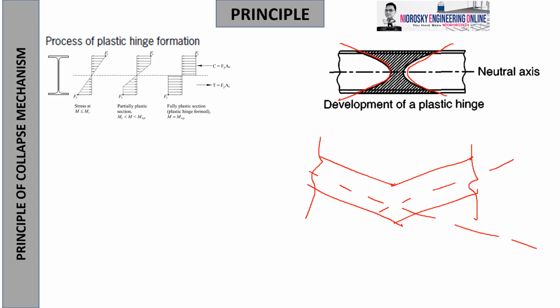Okay, ito yung may kinalaman sa theta sub P, let's say, or plastic hinges. So, dito, meron ditong imaginary ball point na kung saan nagkakaroon ng tinatawag nating hinging. Yan yung pagkatupi in other term. So, yung pinapakita ng region, I'll try to shade it in red. Kinukulayan ko ng pula so that you would better view, or we can try violet para makita. Pinagsama ko ng violet at red para a darker color may exist here. So yan yung portion na natutupi where plastic hinges take place.